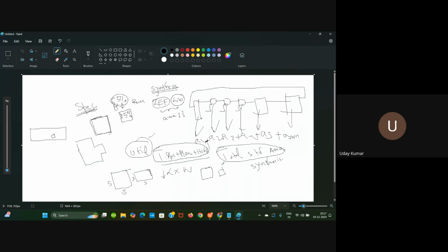And the question you asked was how to fix the core utilization. The fixation of the core utilization percentage will be an iterative process where you will start from a low utilization and go to high utilization. If your design converges and the dimensions get fixed, then you will continue with this to your final runs. Yeah, it's purely trial and error based, sir. Exactly. Understood, sir. Thank you, sir.